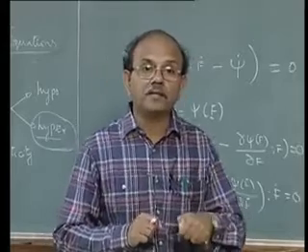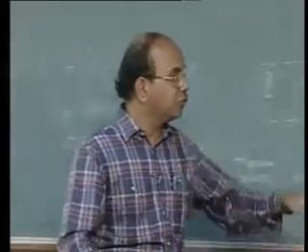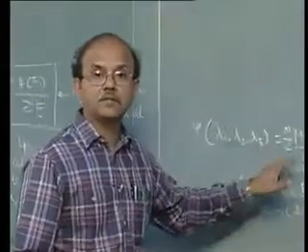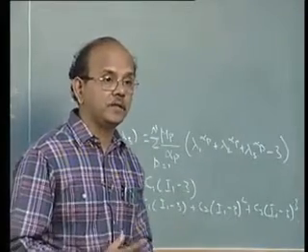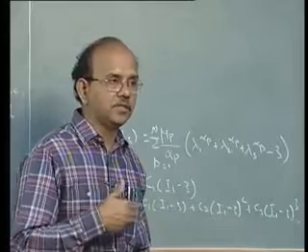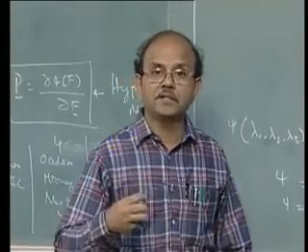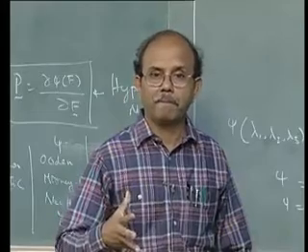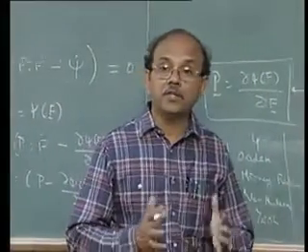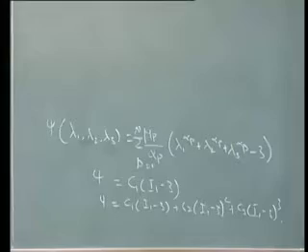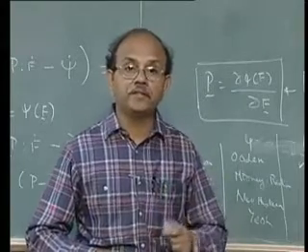In order to apply that, one of the very important things in nonlinear finite elements is that you need constants. Testing of many of these materials is, I wouldn't say difficult, but time consuming, and it requires a lot of effort. Now there are routines available, for example in Abaqus, even to fit these constants.